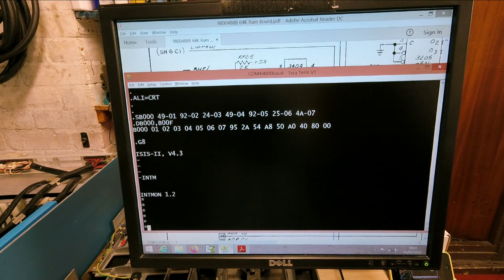So we'll do test 8000 to FFFF. Right, we'll just let it go around a few times. There we go. Obviously it's testing 32K of memory here, so it's going to take a little while. But that looks fine. So I think that'll do it for this video, and I shall see you next time.